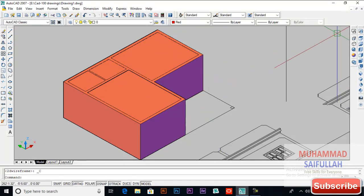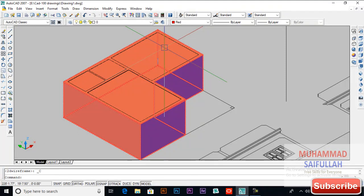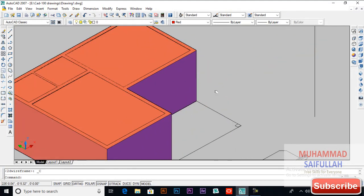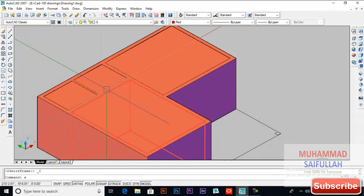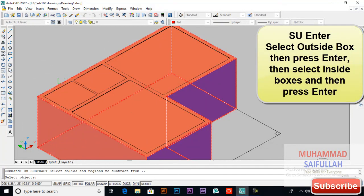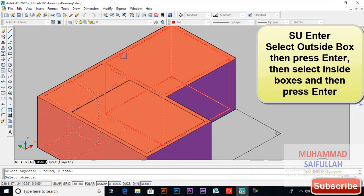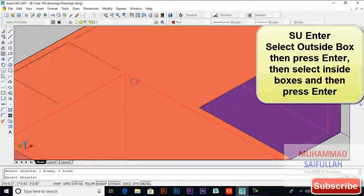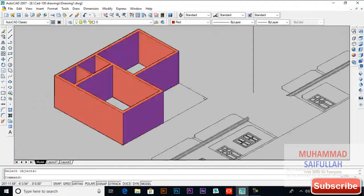Now I will just switch back. If you see here, these are not like rooms, there is no empty space here. So I will do a trick here. You can do it in any style. I will subtract these inside boxes from that outside. So SU for subtract, select your target first. Your main object will be outside, so I will select it, then press enter, then select those inside boxes and then press enter again. So you will see now that these rooms are empty.